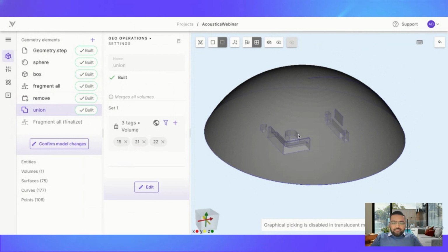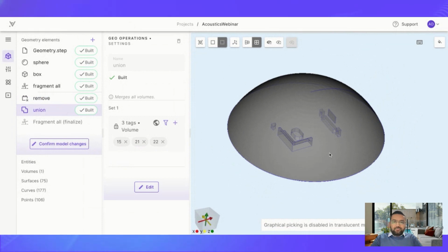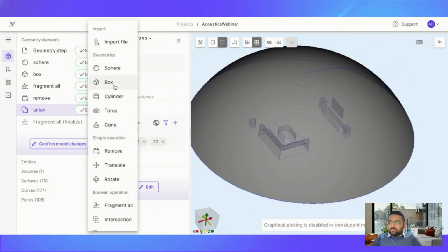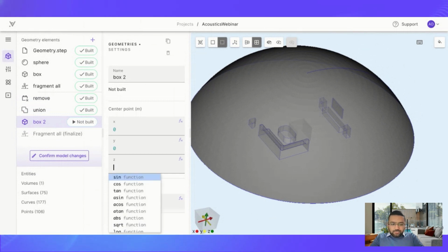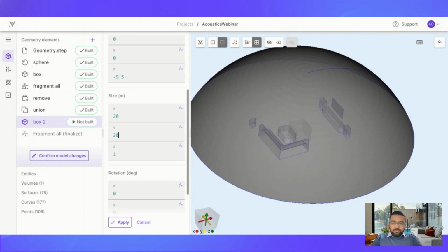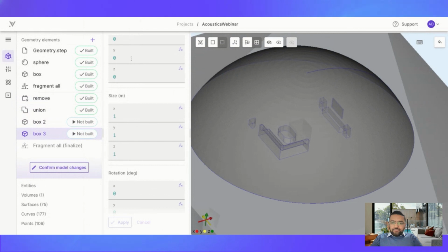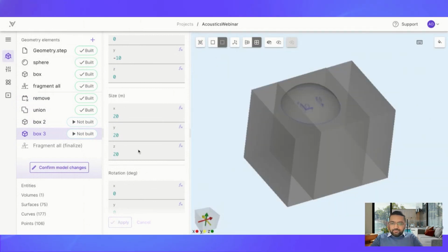But when you run these kind of large simulations, you don't want to dump all the 3D data. So I would like to write the data on some surfaces which I would like to create here. So let me create some box which will cut through this volume, just shifted by 1.5, and another box which is shifted in y direction. Yeah, so basically these boxes.